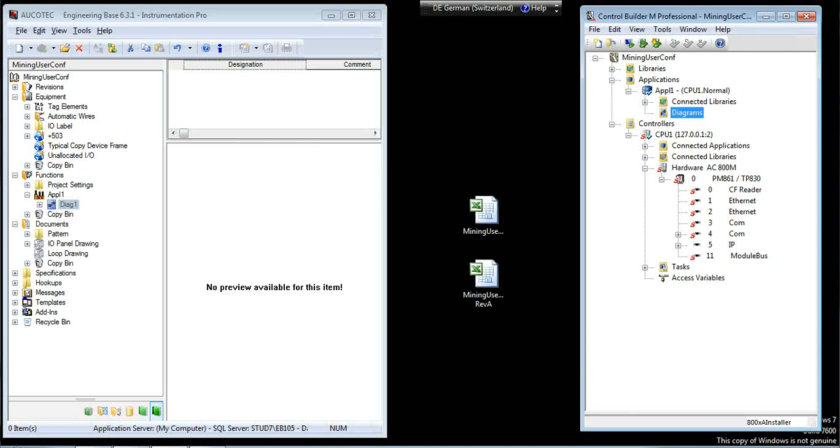We will perform the following engineering steps in this tool. First, we will import customer data such as motor and component list and signal list into the engineering base. The next step is to apply typical configurations in order to generate automatically wiring diagrams, cabling, component lists, and as well the configuration of the application software.